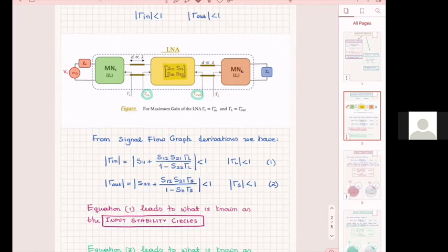You hear that thing, and not only does it keep coming around, but it intensifies. You hear that a lot of times when people use a microphone to speak, and all of a sudden it goes off and the volume keeps increasing. That's when you get positive feedback into your system. So your amplifier keeps receiving higher and higher input, and of course the output is going to keep increasing, and that's when you have that.